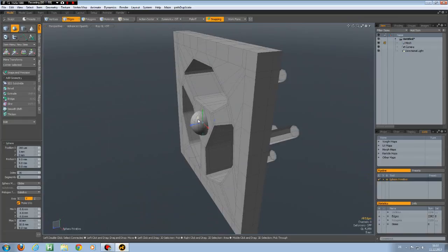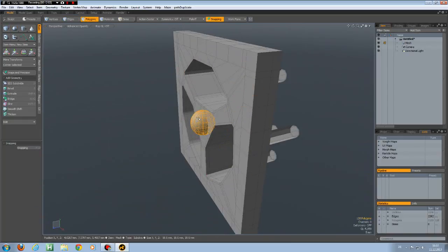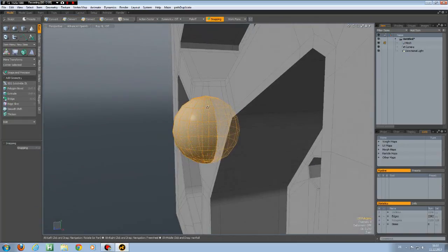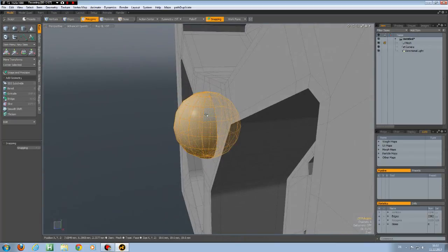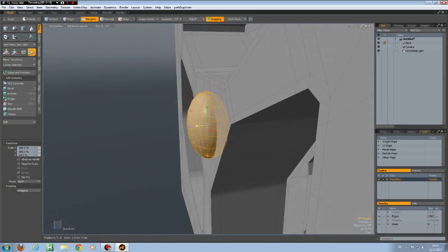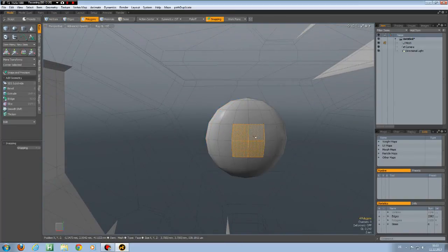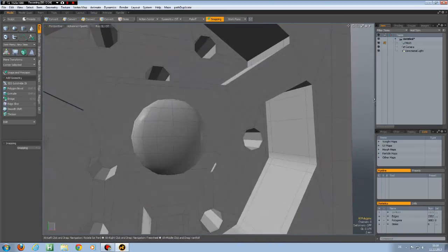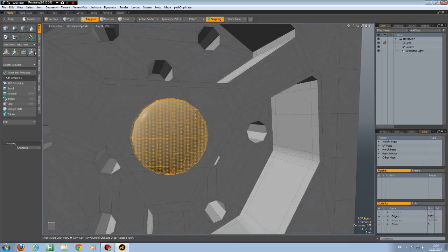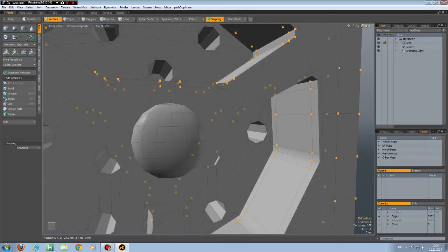Perspective, select the sphere, go out of sub-D mode by hitting the tab key, R key, make this flat and push it in a bit, like so. From the back side, Shift up arrow and delete, and I put this center selected in X and Y. Yes.